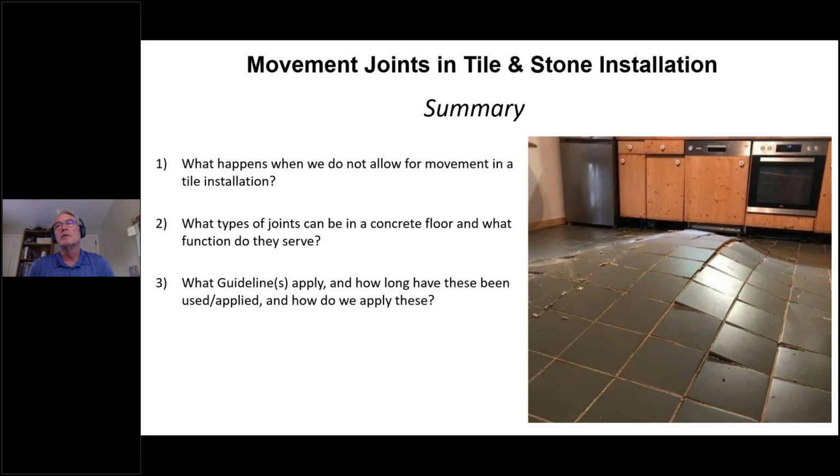The other part of that was what, Jim? Backer board? Using isolation membranes and backer board for managing movement. So there's no standards for that. The TCNA handbook and ANSI are very clear. You just follow TCNA and ANSI, and there's no recommendation or accommodation for movement joints, because you're going to put a crack isolation membrane in there.